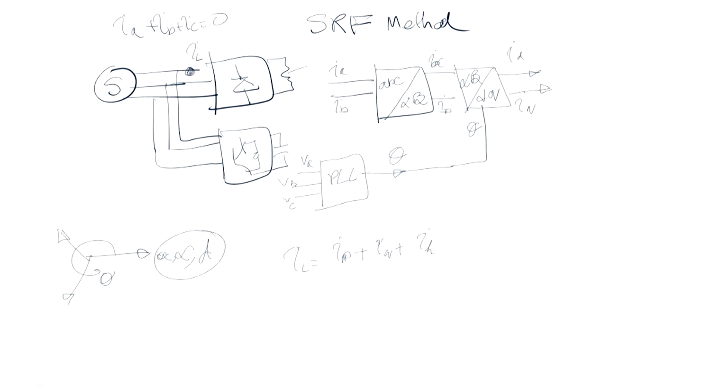Generally the harmonic is from 2 to infinity, if I write, it does not matter, but you know that Ih is essentially the 3rd harmonic, 5th harmonic and so on. The 3rd harmonic will not be there because you do not have a neutral. So, it will start from the 5th, 7th and so on.